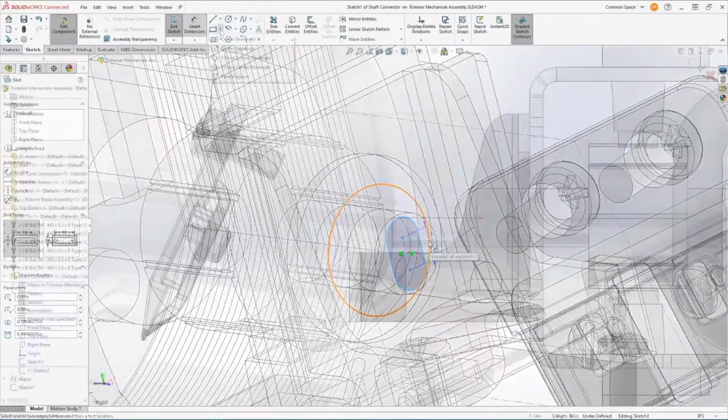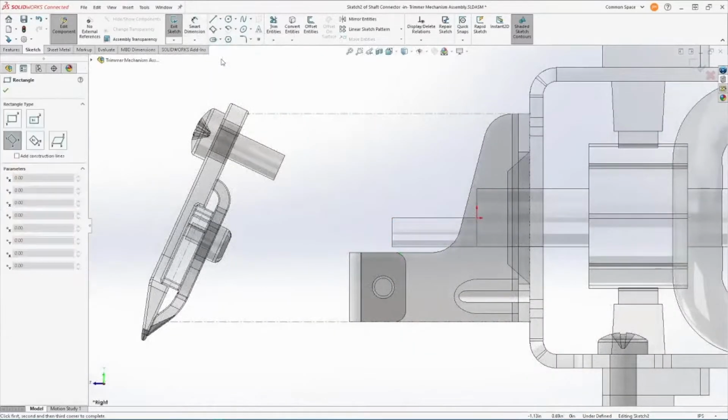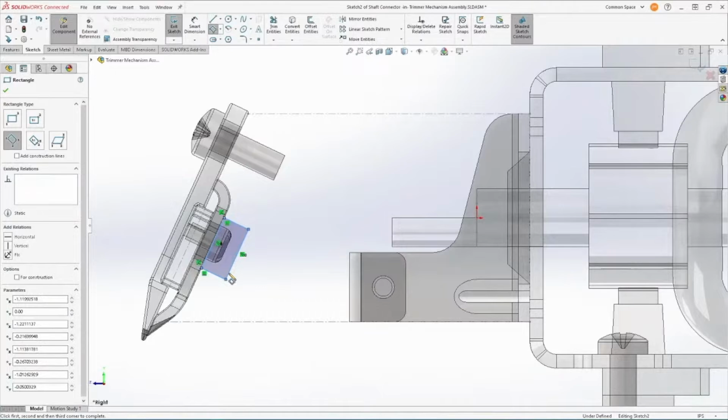Let's keep it going. Alrighty, so the next sketch will be the side profile. What I'm actually going to do is attach the sketch to the bottom blade. That way, if I adjust the orientation of the blade later on down the road, my component will update with it. So this is just best overall design intent to avoid making unnecessary changes later down the line.